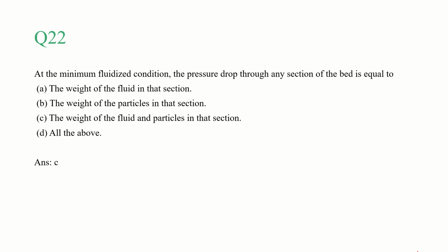Okay. At minimum fluidized condition, the pressure drop through any section of the bed is equal to. Okay, these questions are just practice problems. So if you are interested, you can just solve these. Yeah, just for general knowledge. At the minimum fluidized condition, the pressure drop through any section of the bed is equal to weight of fluid and the particles in that section.